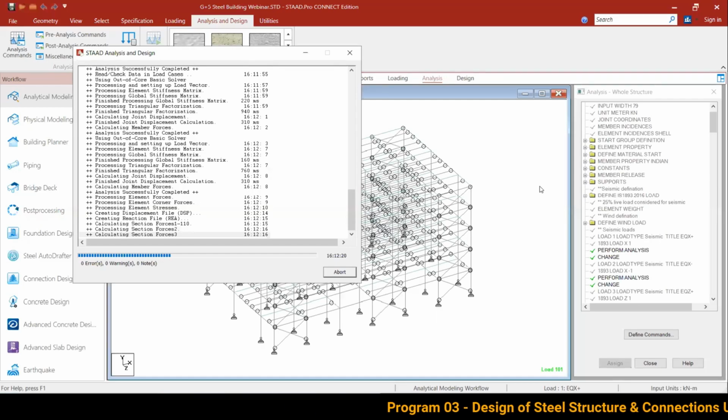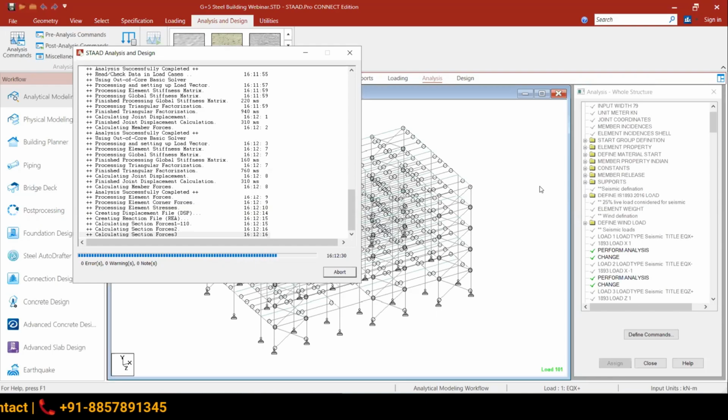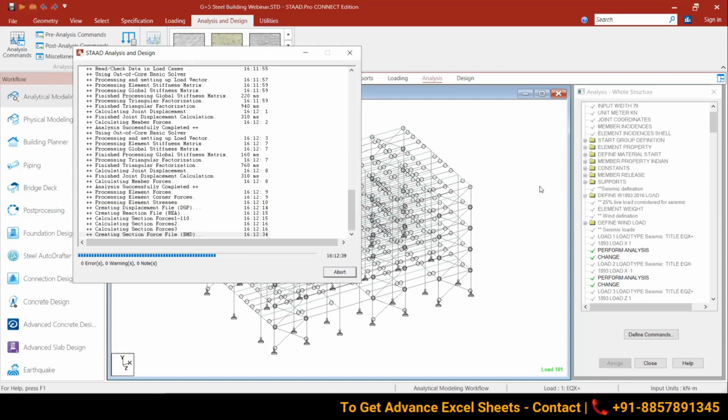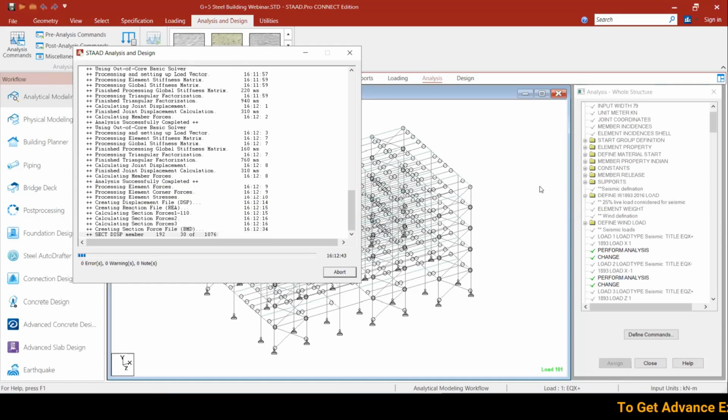Till the analysis is complete, I want to ask another question. Usually in a steel building we use a composite floor decking system for the concrete plate. In that case, are there any options to model and design those composite floor deck panels in STAAD Pro? I think one option is to model the plate and then mesh it so that the plate also acts as a structural member.